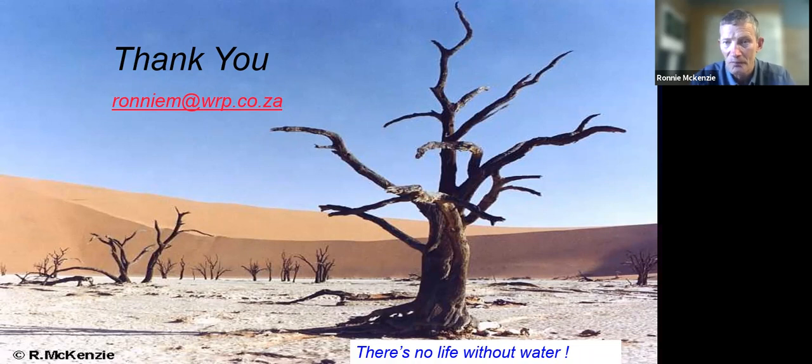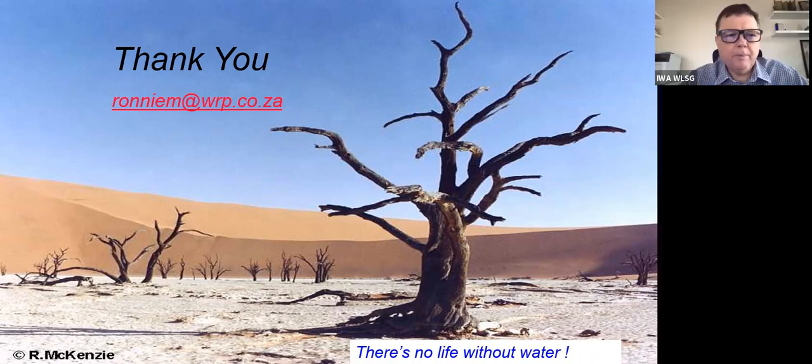Water's too precious. And I don't know where you're based, Stephen, but one of the key things you have to think about is whether your water supply to your customers is direct or whether it goes into a tank first. If it goes into a tank first, then reducing the pressure won't make any difference. The customers will still use the same amount of water. It's only in some countries where people are doing, like Ronnie says, irrigation direct from the main pressure that you would see some reductions.